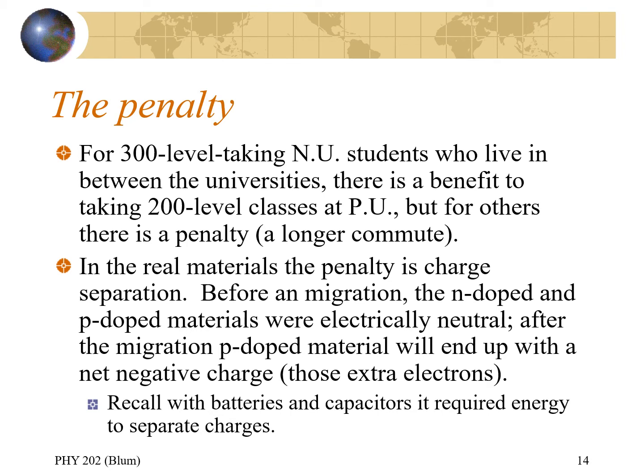So before anything happened, when we had n-doped and p-doped materials separately, each one of those is electrically neutral. So we might think of there as being extra electrons in the n-doped, but those extra electrons floating around also came with the corresponding nuclei that had extra positive charges. And so it was neutral. Same thing for the p-doped. We might think of there as being fewer electrons, but it's not really fewer electrons, but fewer free electrons. And that condition of fewer free electrons came with a reduced positive charge than corresponding. So everything was neutral. The n-doped material was neutral. The p-doped material is neutral.